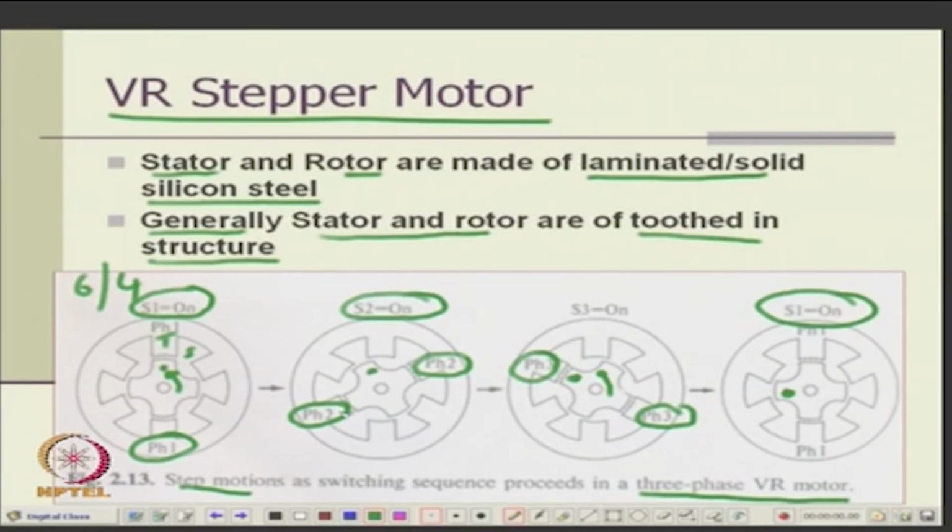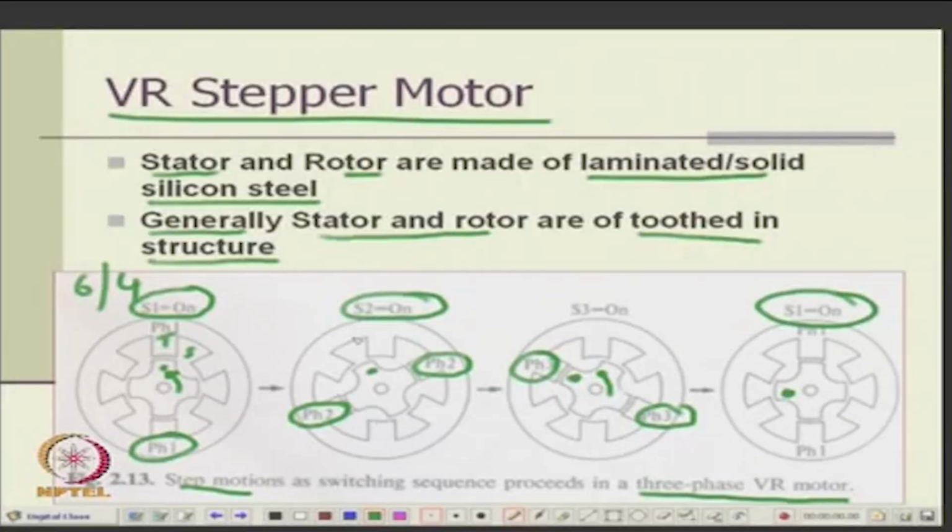How is it different from variable reluctance? In a variable reluctance machine you normally go for high frequency switching, there you require continuous rotation and producing a torque. Here you are happy if it just moves and keeps quiet. So, its movement is in steps, at low speeds and low frequencies, and it is low power. Basically a switched reluctance motor is a big stepper motor, carrying big currents, big voltages, big circuits, big torques and big power and continuous rotation. Here everything is small, and it is only for movement like valve control or opening a gate, or something like that.